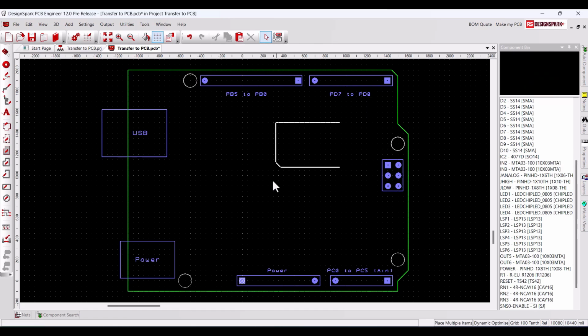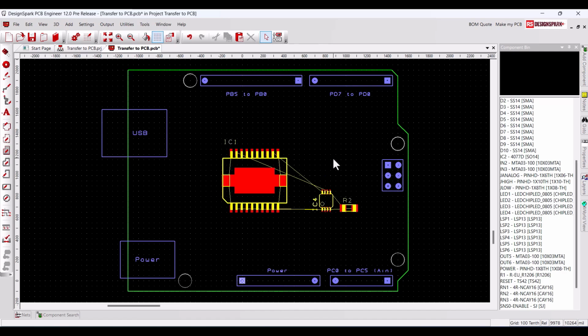Click and drag onto the PCB editor and these are ready for placement. Net connections are shown for the selected net plus any other nets such as the supply and ground between the selected components, which makes the choice of component location and orientation simpler.